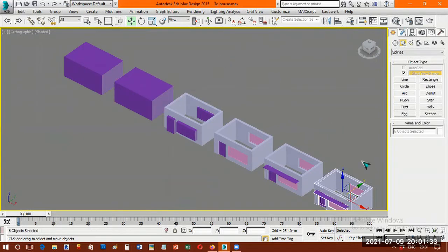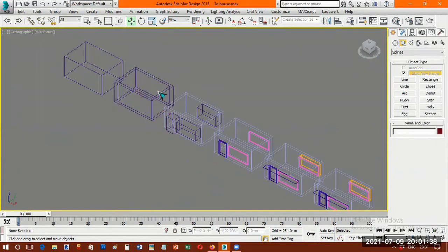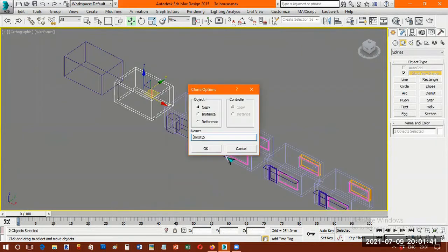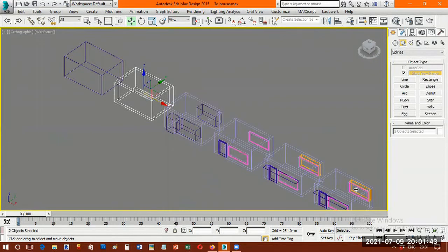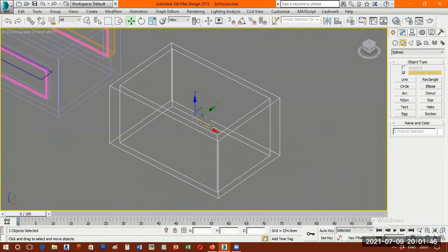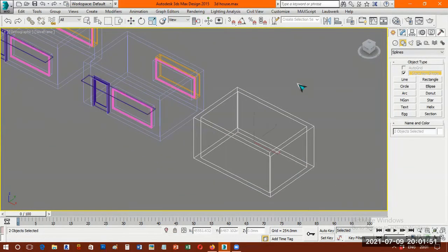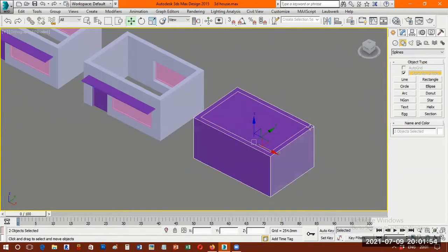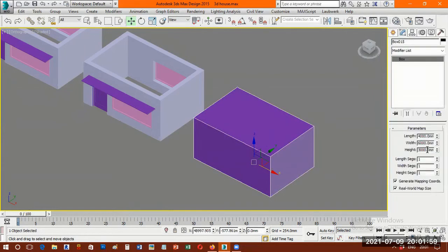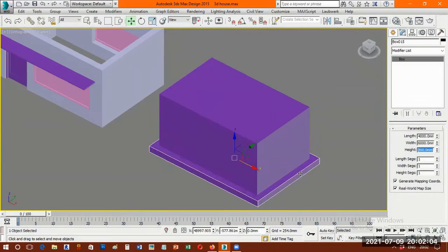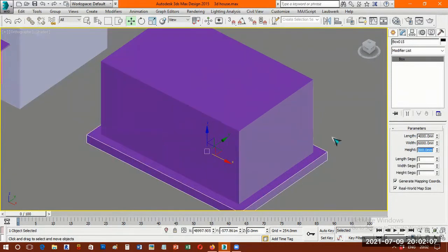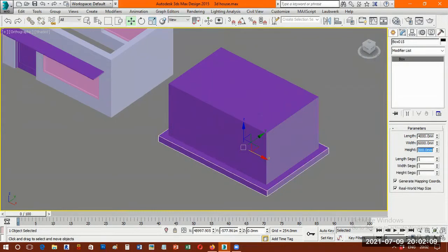Now how to get that box place roof is, let me have the double boxes we have taken here. Now these two I will copy, Control V. Now these two boxes only I can convert into a molding or a roof or a parapet. Let us see this. Now there are two boxes. The outer one I will select and reduce, go to modify and reduce height to just 300 mm. Enter. I hope you can see that box height is reduced to 300 mm. Now, fine. Now I'll place that on top of this, which acts as a roof.